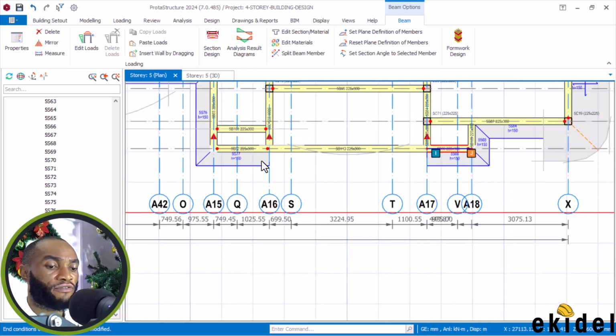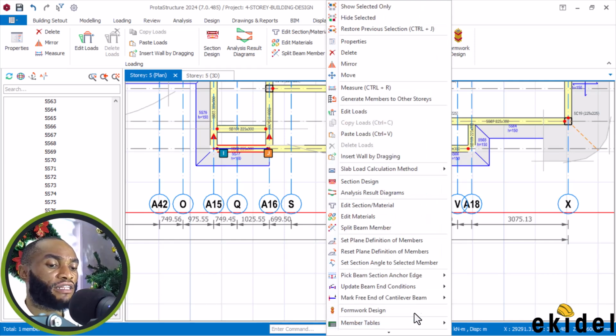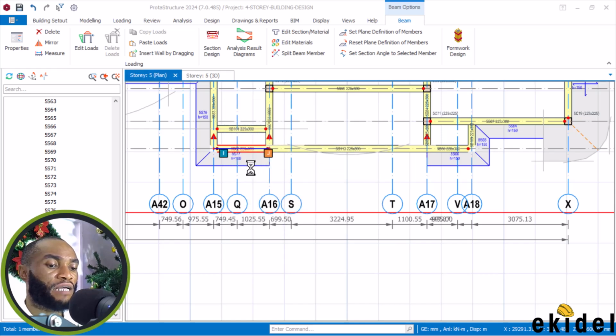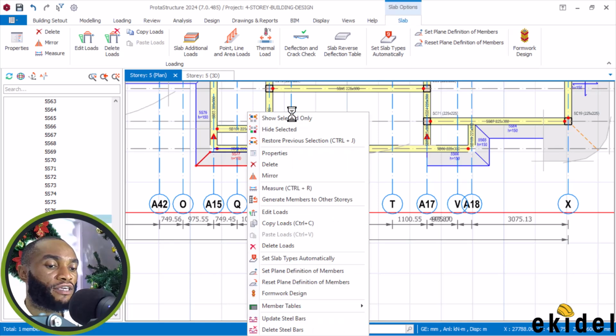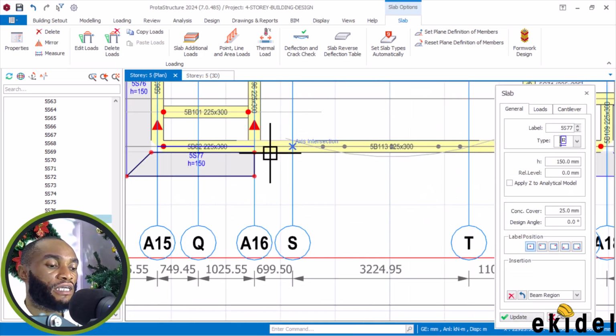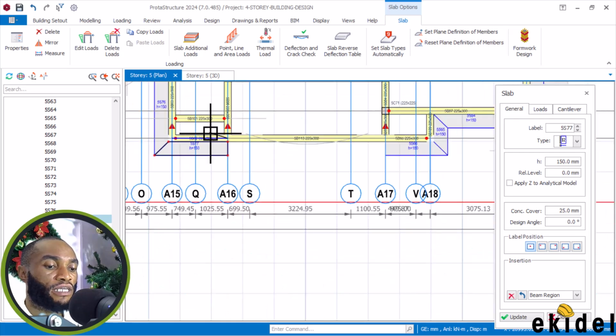This is that one too. We still have the same thing. Right click here, hinge at only the I end and say apply. Then come here now and right click here, properties, to take the parapet properties. Then come here and click here, that's fine.